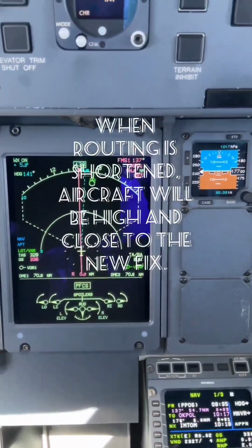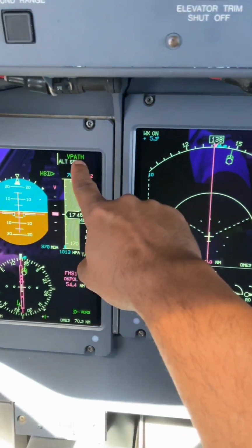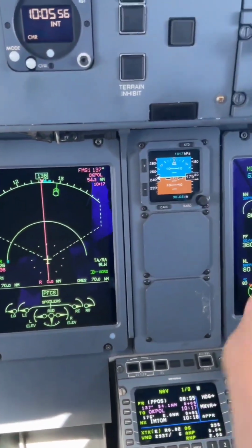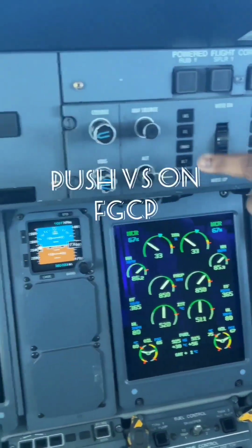So what Marcin is going to do now, the first thing you've got to do is to disengage the VPATH and use vertical speed. So Marcin is going to press vertical speed. There it is. Like that.